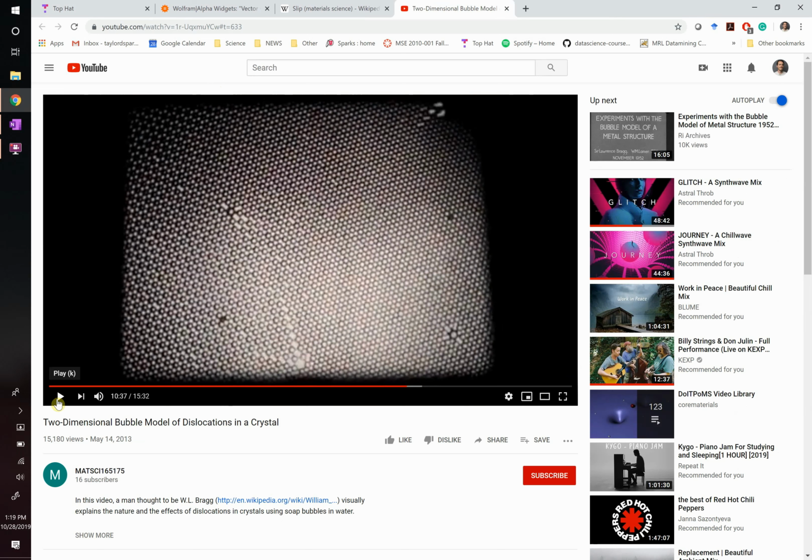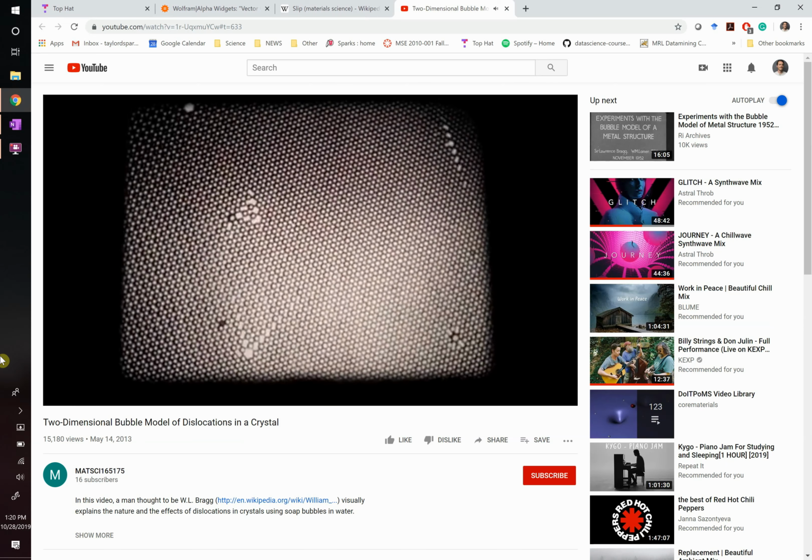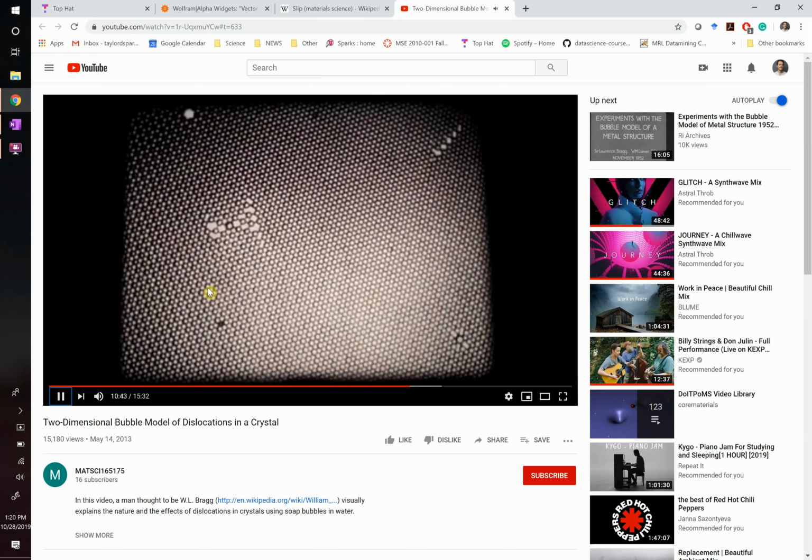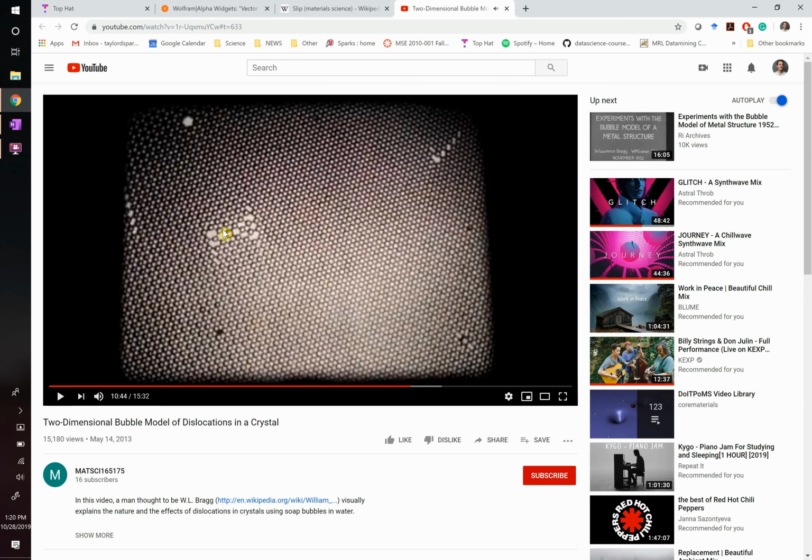Now watch what happens when a dislocation comes in the vicinity of that. What's in the vicinity in terms of a strain field of a too big of bubble? It's under compression. So what side of the dislocation is going to want to interact with it? It's going to be pushing away the compressive side and attracting the tensile side. So one of these dislocations comes, and watch what happens. As it comes, it pins it, right? On either side, the tension region of two different dislocations are pointing towards that impurity because overall, they have these tensile regions that they'd like to fix in the lattice, and you've got an extra big atom, so it's going to sit right between those.